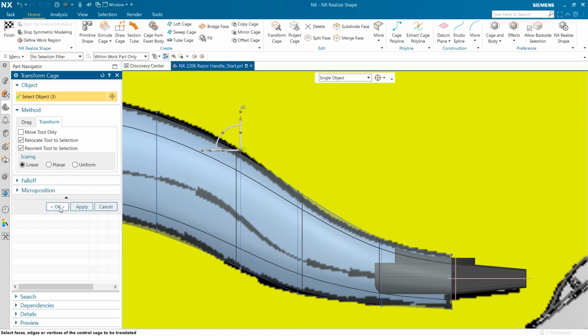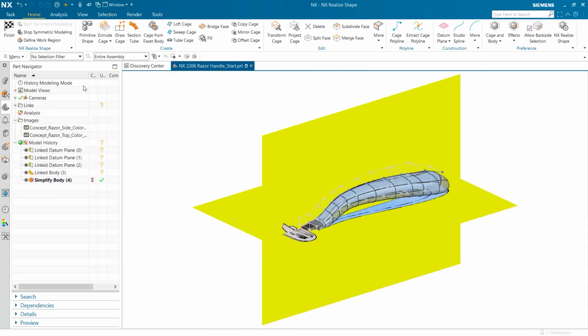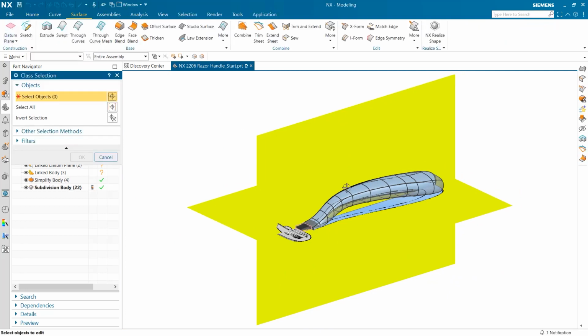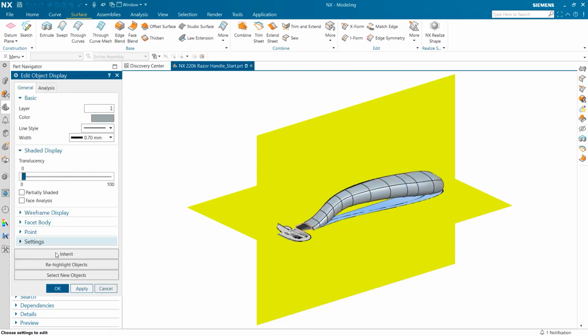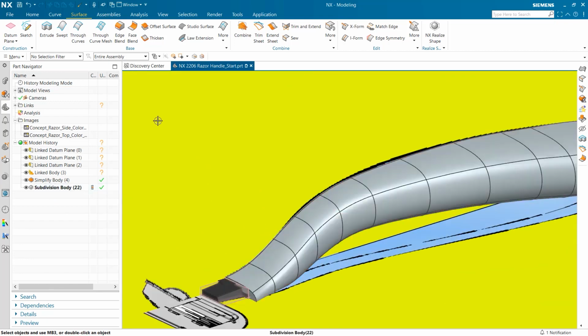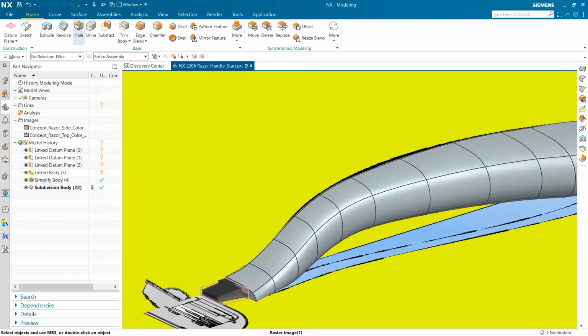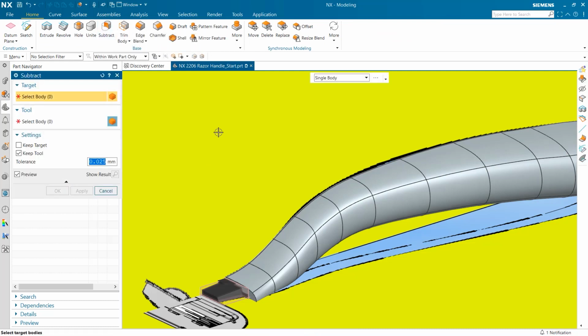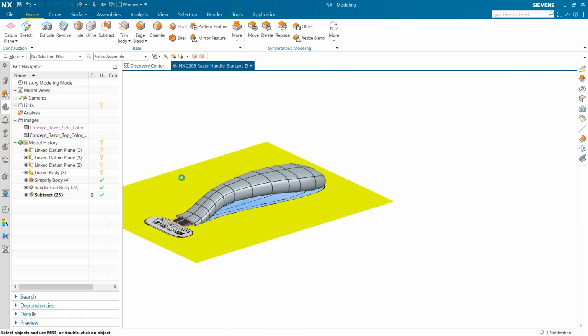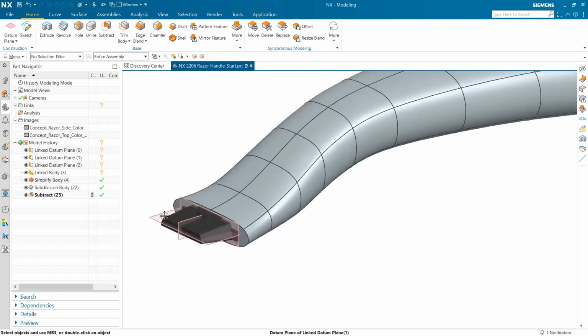Once you exit the NX Realize Shape tool, the previous steps used while in Realize Shape are stored in a subdivision feature. This feature can then interact with other forms of modeling. In order to create the recess in the handle for the razor blade connector, I can subtract a body that represents that. During the subtraction process, I am maintaining the tool body so I can use it downstream. And I am just using standard NX modeling features to do this, so I'm combining Realize Shape with standard NX modeling features.